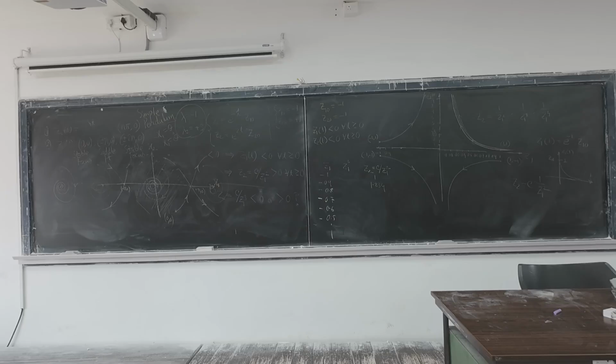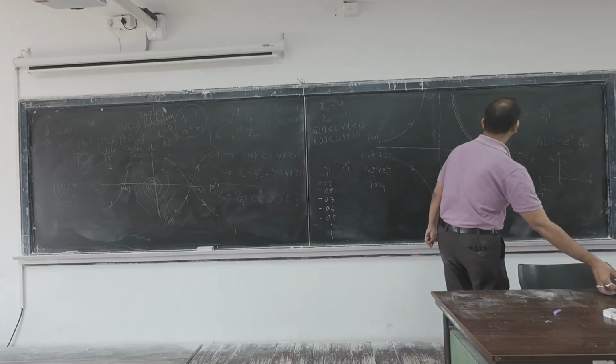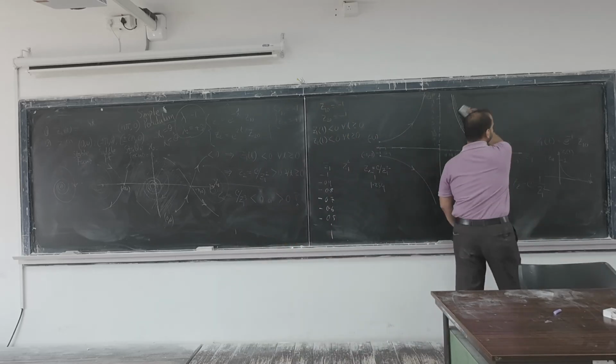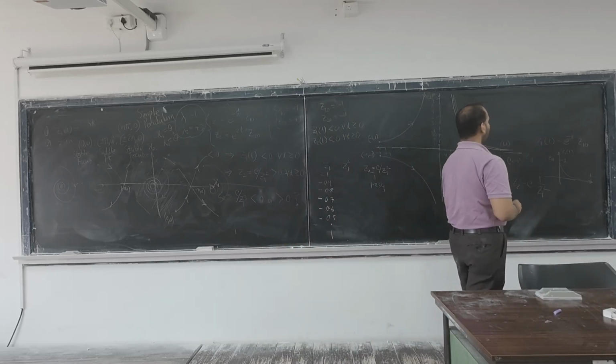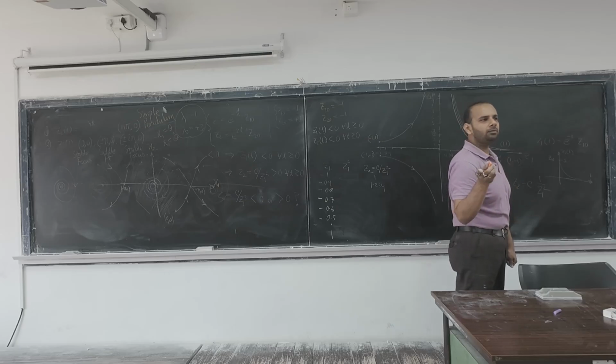Now, what about the operation? If you have a DC-DC converter, which is called a step down chopper, ultimately the output voltage is the average over the switching period. What is that situation? This is an interesting example for any kind of converters. I hope all of you know about DC-DC converters, like step down chopper or step up chopper.